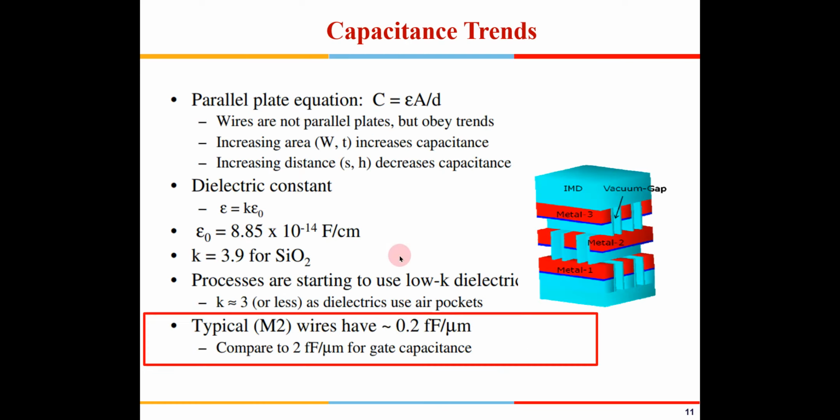In the case of capacitance, the capacitance is defined as some femtofarad per micrometer of the length of the wires. Now generally it is 0.2. Now we might be thinking, why is the width of the wire not scaled here? Only the length of the wire is scaled here. So you just keep a note of this. I will explain this aspect in the next slide.